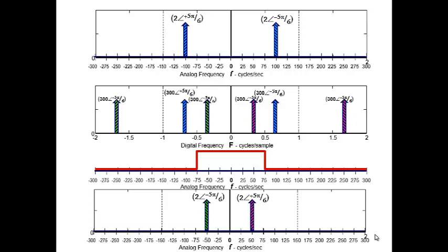Professor, how did you determine the cutoff frequencies for the filter? For this guy? Okay, this is going to be a low-pass filter. Its job is to throw away copies of this frequency spectrum that are outside the Nyquist rate, and so I'm setting its cutoff right at the Nyquist. This is what we called the principal range, because if I know this, everything else is a copy of it.